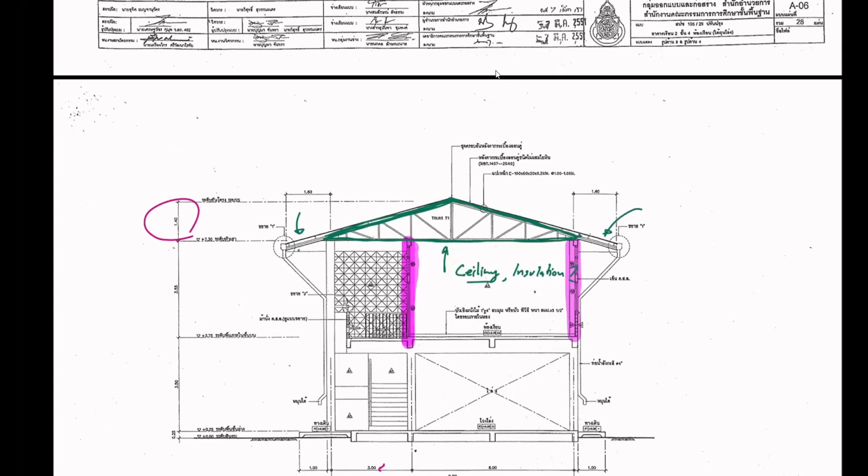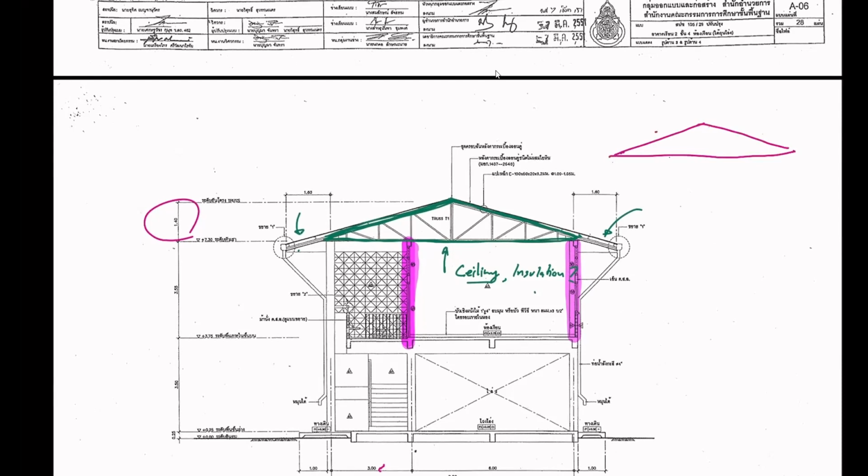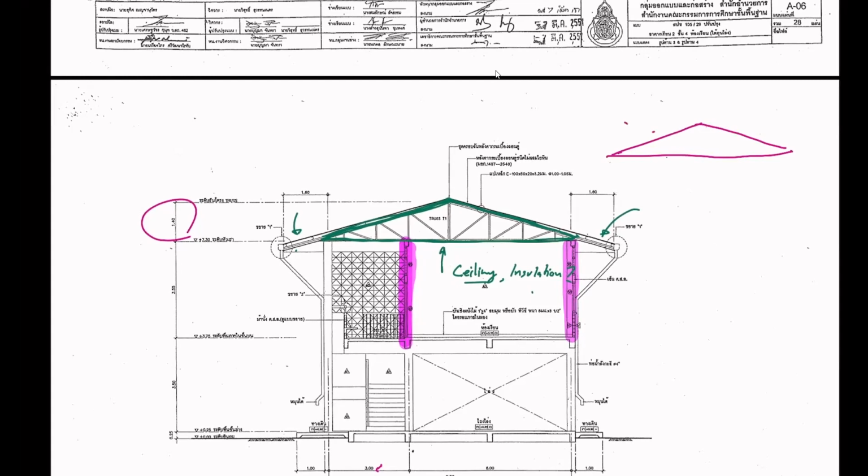But if it becomes necessary, what we can do is this as well. It's going to be very difficult to draw. Say you have a purlin coming in here, on the top chord. You can extend something from the purlin to brace the bottom chord as well.